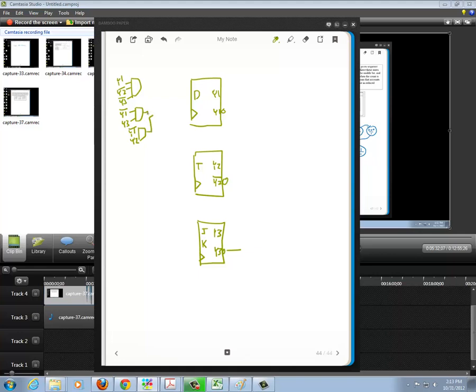And we're going to put these all together into an OR gate, and that's going to be our D signal. So these, again, you could actually draw a wire coming from this feeding back around. So wherever you see Y1, it would be coming from this Y1. If you see Y2 not, you could grab it from the Y2 not and draw it back around. But as you can tell, it's going to get very messy, so I'm not going to draw it like that.